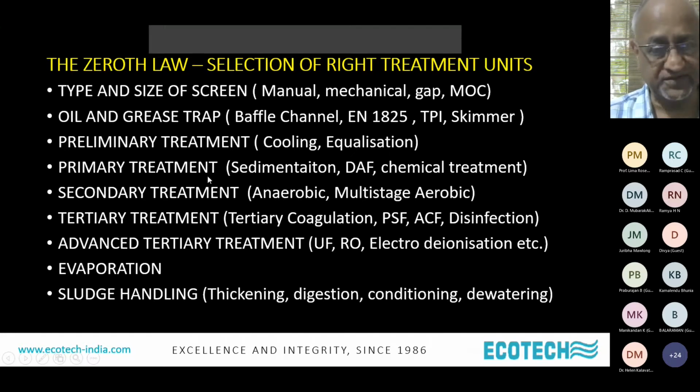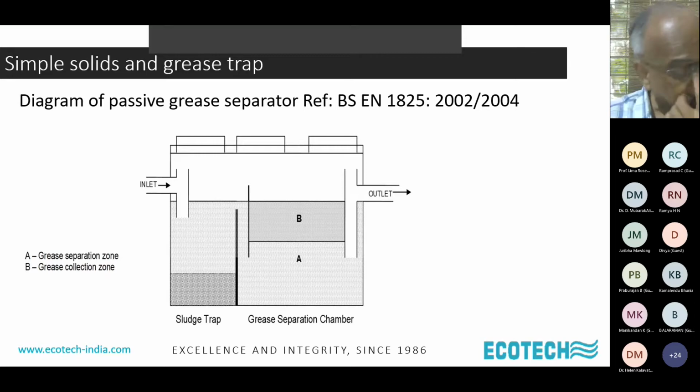So all these different treatment technologies, treatment units, and facilities are available in the hands of an ETP designer. So it is your experience, your expertise to select the right mix of all these for that particular application which you have in hand, and to meet the quality standards specified for the treated wastewater. So you need to have a lot of experience in handling that particular waste. And if you do not have previous experience, as I said, you will have to resort to treatability studies.